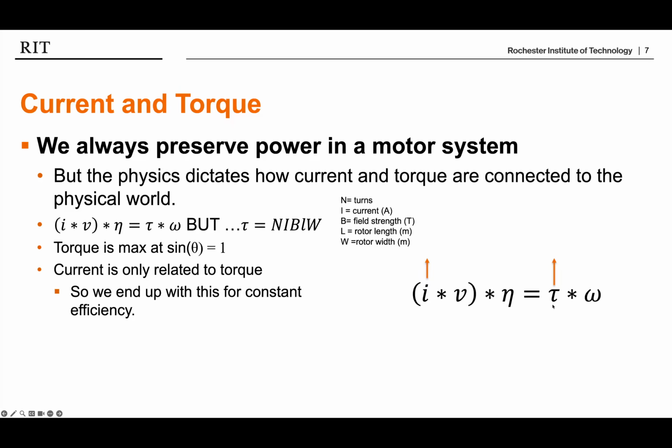So as my torque demand increases, my demand for current increases. And I say that in a very, very specific way because this really is about torque demand. Motors demand current when they need torque. You cannot take a motor and just turn up the current and get more torque at the same RPM. That is not possible. You can, however, give a motor too little current at a given RPM to achieve its